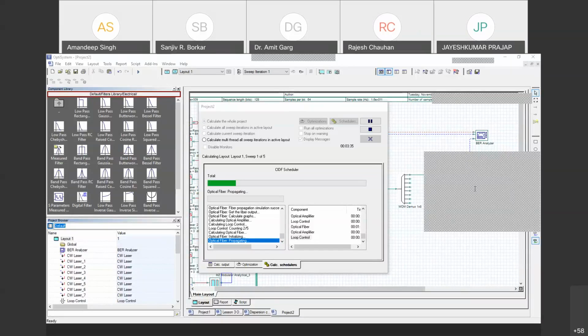Yeah, very well. You can use OptiSystem for underwater wireless optical communication. You can go through different types of IEEE or Elsevier papers. They are purely written using these OptiSystem simulations. For that, you can use the FSO component and its terrestrial links, meaning you can change the scintillation effects, gamma or log normal. These are some of the atmospheric conditions you have to take care of. Yes, this is possible.